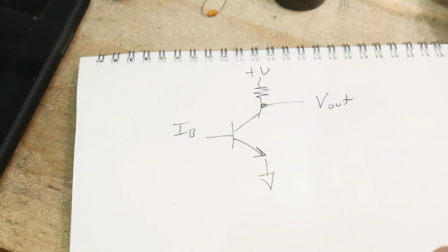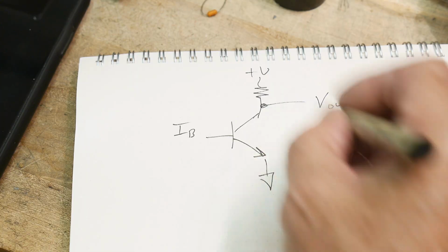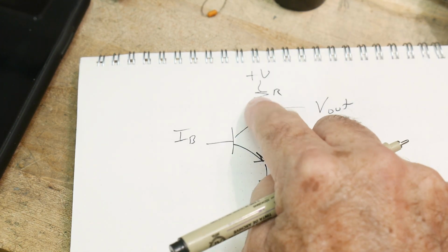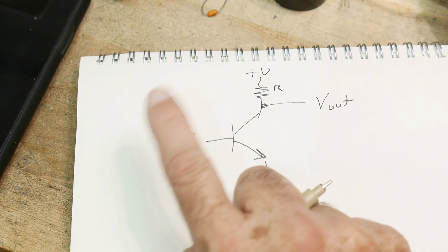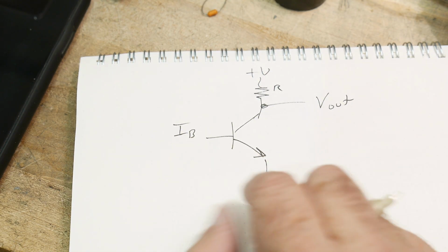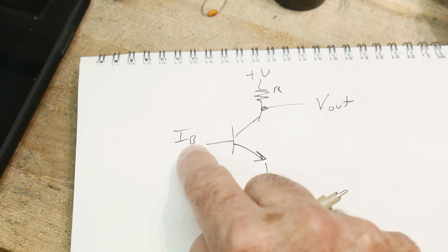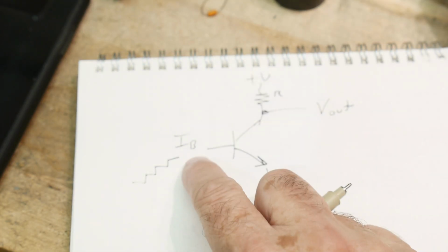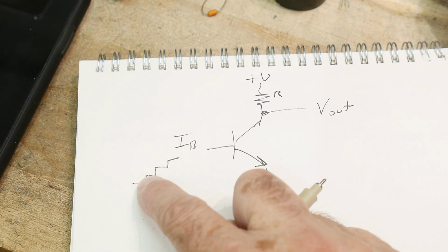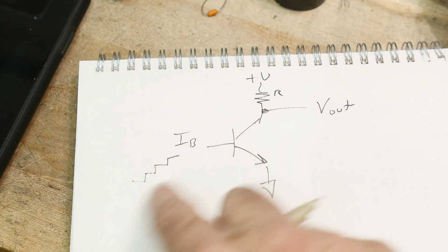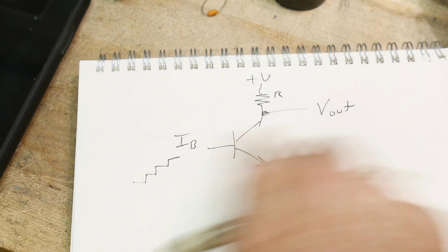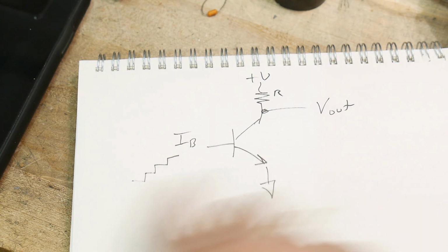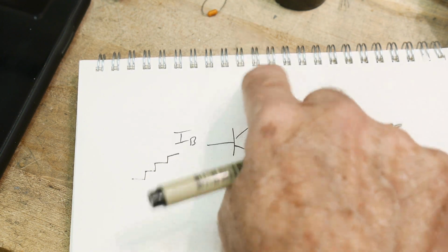Okay, well, I don't know if that hurt or helped, but this is the circuit that we're always testing on the curve tracer. We get to choose the R, we get to choose the V, we get to choose the current coming in, and we get a picture. We hold this constant, or we make it a family of curves. We can put a step in here. We can have, say, 1 milliamp, 2 milliamps, 3 milliamps. We can step this. And this voltage sweeps back and forth, 0 to 10, 0 to 100, 0 to 1500. We can make it go back and forth, this voltage here.